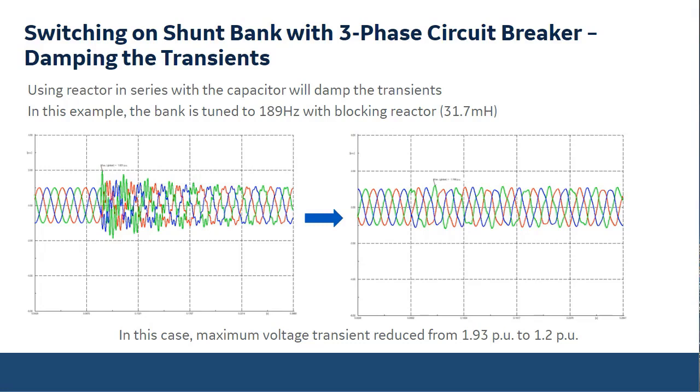If there are any problems, it's only with a very few to withstand, in my opinion. So this is the way to go if you have any kind of voltage transients. You need to add inductance in front of the capacitor, and then it should be taken care of.